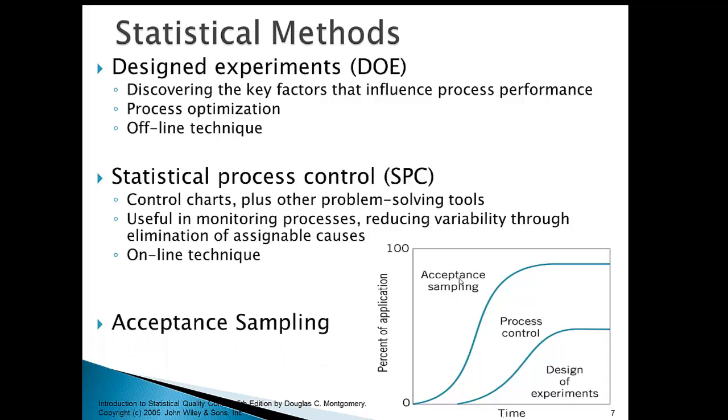And then lastly, acceptance sampling. That's based on incoming inspection. So we'd be taking 3 pieces out of 1,000, and if those 3 pieces are okay, then we say all 1,000 are okay and pass. If one of those 3 pieces is bad, then we say the whole lot has to be inspected before we can move it forward, or maybe just reject it back. So there's some statistical analysis in coming up with what those sampling plans are, but the sampling plans have all been developed for us, and so we'll take a look at that and apply that later as well.